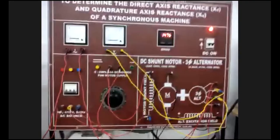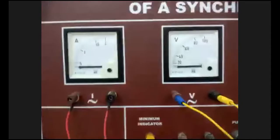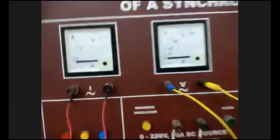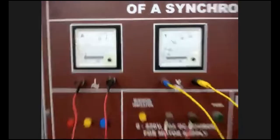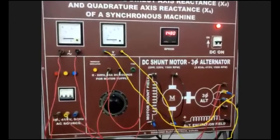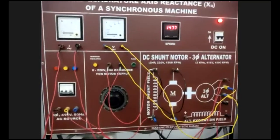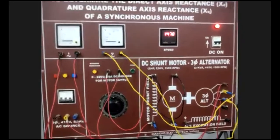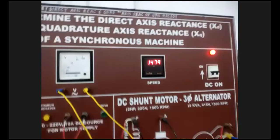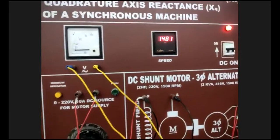Okay. Now what can we do? Now look at the ammeter and voltmeter reading. It is showing 0 because we did not give the supply to the three-phase induction motor. Now what can we do? Switch on the AC supply of three-phase. We will switch on the AC supply now. Look, the speed is now 1480. Okay, no problem, no issue.